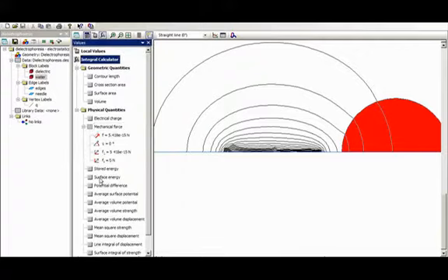And the force acting on the particle is roughly 5 femtonewtons, and that's the z component of the force, so that's pointing along the right. Okay, so this is pointing away from the needle here, so that the particle is repelled from the needle in this case. What I'd like to do is interchange the roles of the particle and the medium and compare the force in that case. So I'm going to go back to the model file.